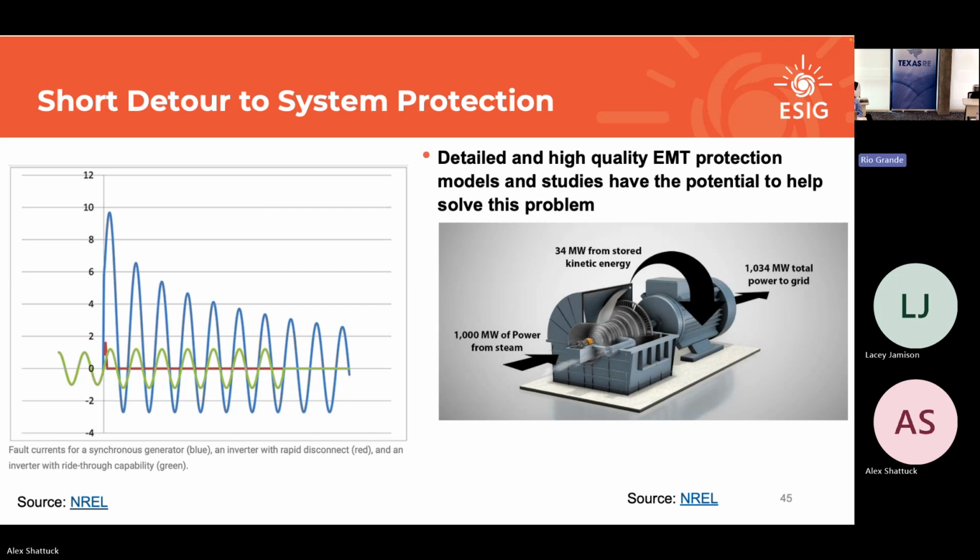The reason why I have it in here is that highly detailed, high quality EMT protection studies can help us out. A really specific use case: we do need actual EMT relay models with real code, because the entire system protection paradigm is basically rooted in fault current. Big generalization, but a lot of system protection engineers depend on the paradigm of having a lot of fault current available. With a lot less fault current available, we're opening ourselves up to missed operations and things like that. And maybe we don't trip on that anymore.